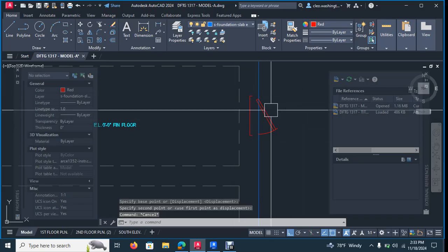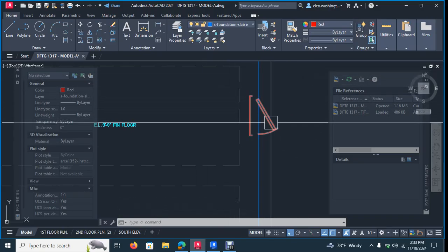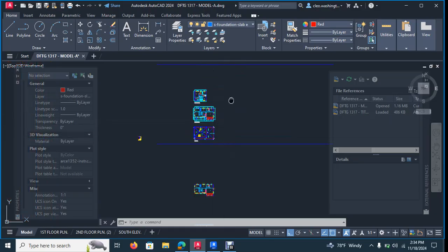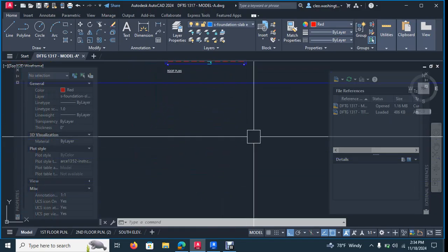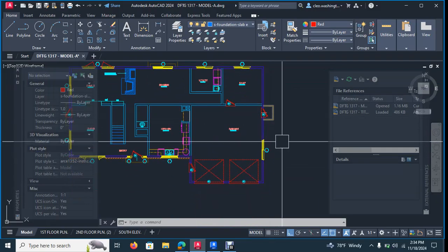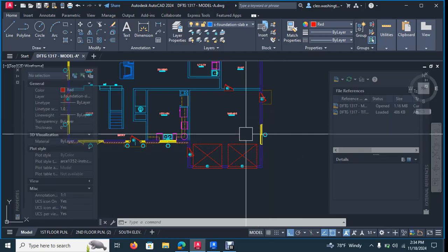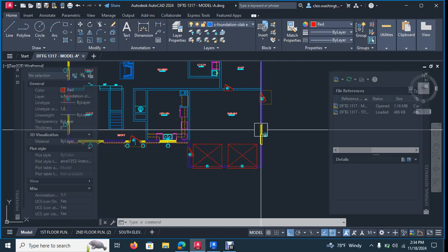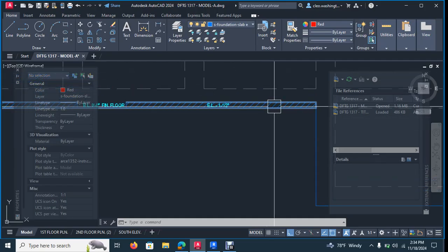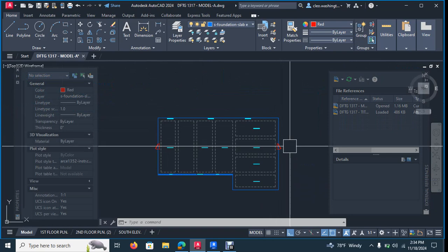Okay, so this door, the way the condition works where there is siding, the siding goes down. If you go back to your section drawing, you'll see the siding actually goes down and goes by the exterior of the slab. So there's no slab edge to house the siding because it's attached to the building with nails, right? As for the brick, we have to actually have a brick ledge to house the brick, okay? And then again, I'm going to have some addendas, guys.